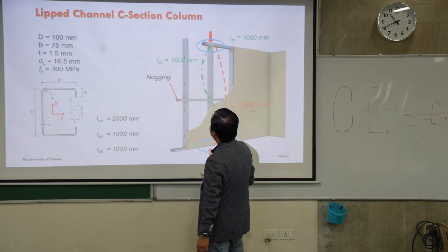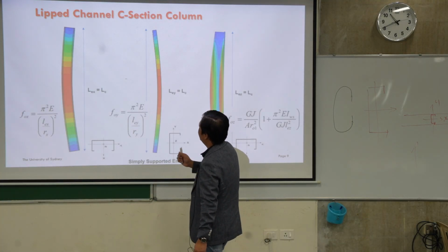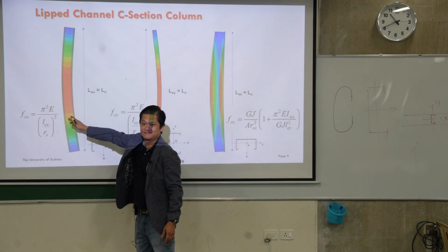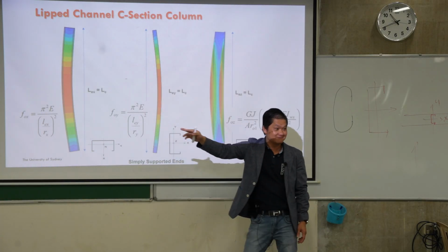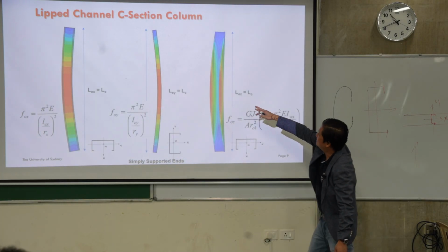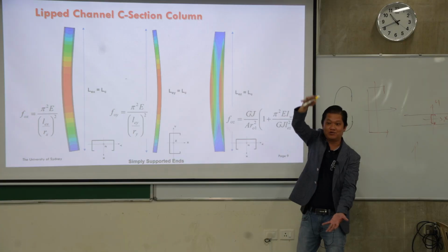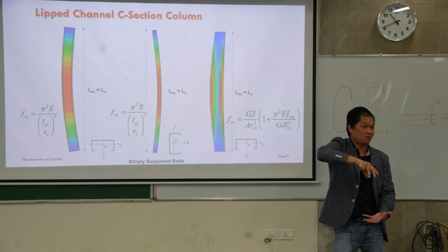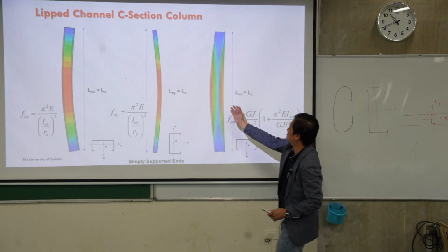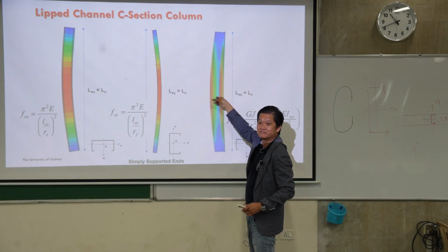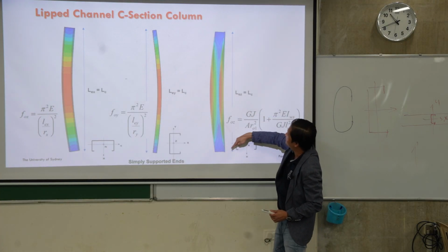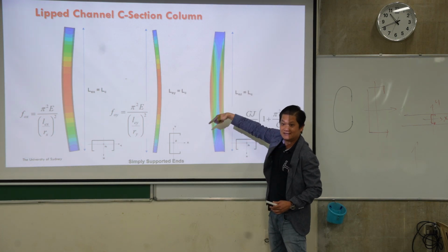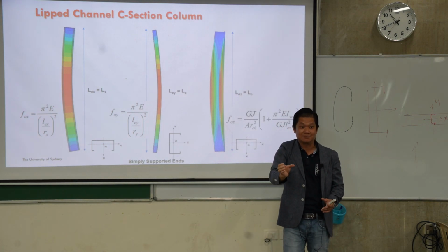Now, in terms of X, everyone happy? In terms of Y, everyone happy? But you can see here that's twisting. When you push that one down, it twists. Looking now, it's purely a twisting moment, torsional, and you can see the cross section twist. The twisting now is a half sine wave in terms of the twisting displacement.